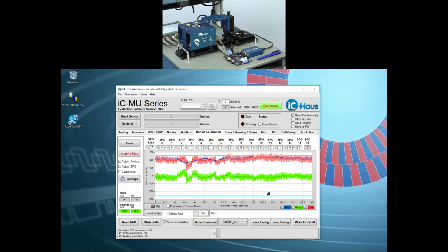And the last step would be you just write your calibration parameters to your EEPROM here, and that means you're finished with the setup. And on the next startup of the chip, basically, the chip will be able to read all these parameters and is calibrated again.